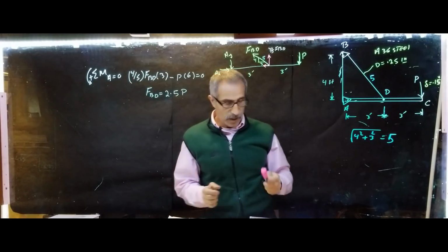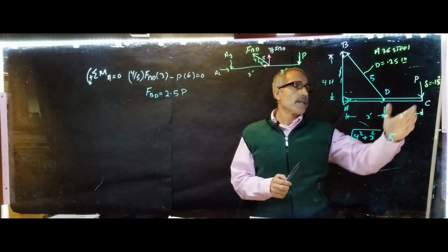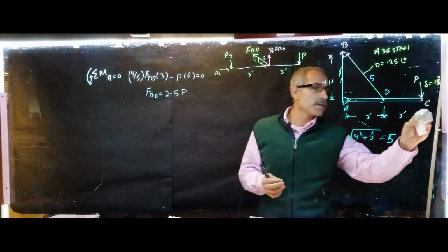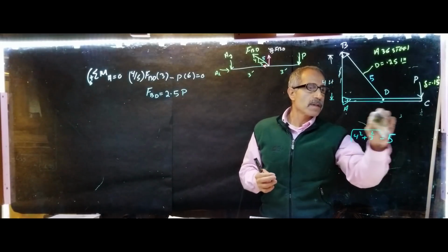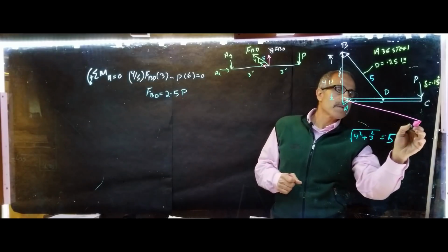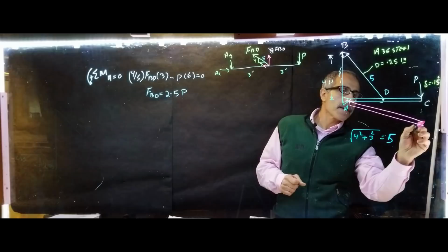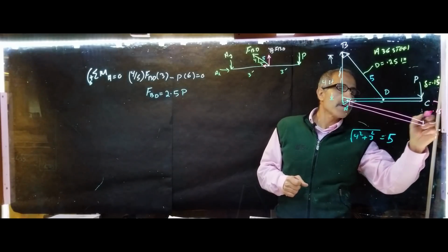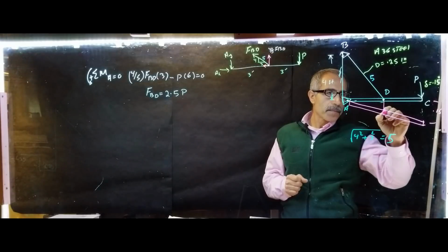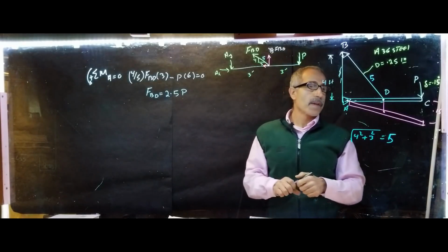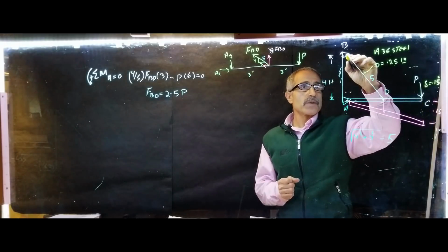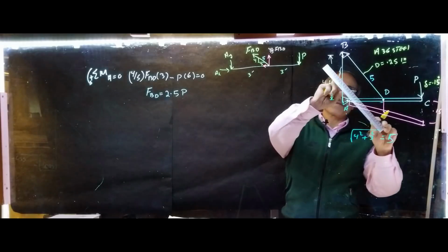One thing we have to notice here is that this is deflecting by 0.15 inch. Let's exaggerate this. Actually, I need to erase this stuff a little bit so I can have room. Say the beam comes down, exaggerated, and this is 0.15. I'm really more concerned about right here. What I'm saying is that the cable is going to stretch. If this is going to come down 0.15 inch here, the cable is going to stretch from here.